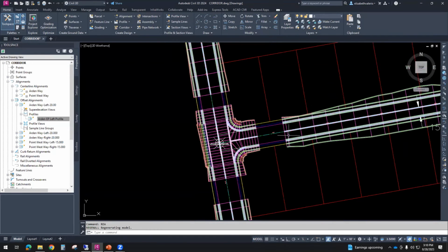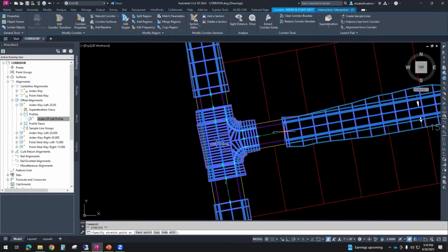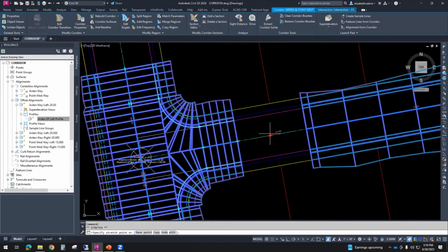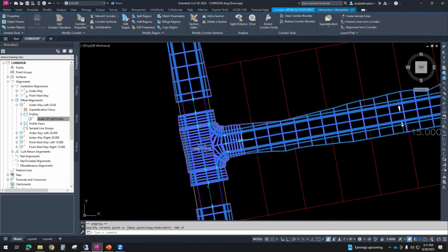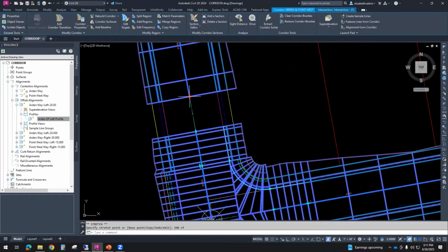Okay, so you can click on the corridor and you can use the diamond grip to slide the corridor. For everyone, we're going to be sliding them so that they snap to the end of the intersection piece. So it should match up when you slide them in.